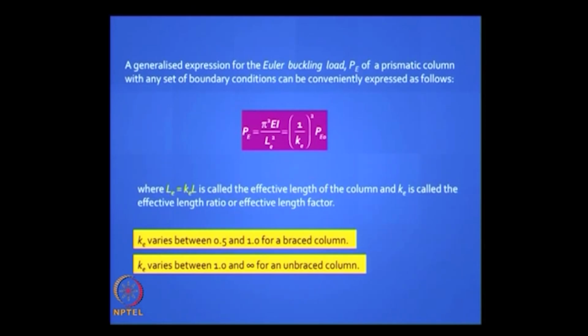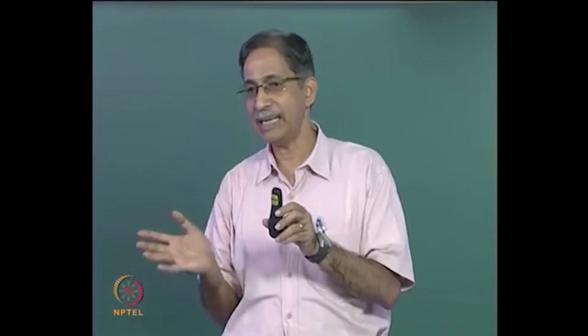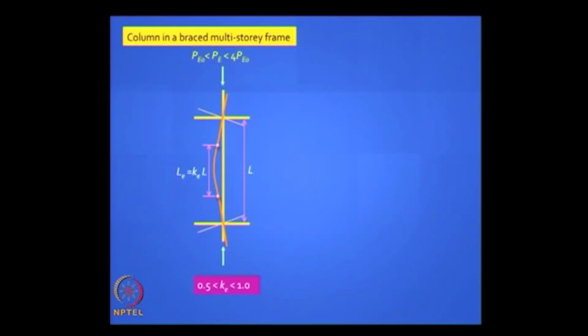You will have 1 when you have a guided fixed support at the top and fixed at the bottom. In a cantilever, it's going to be 2. And when do you get infinity? If both ends are pinned, it's unstable. Okay, so that's the other. Let's say you have a beam, you have a multi-storied building in a column, and the column has pinned ends. That means the beams have 0 stiffness. Then that's asking for trouble because it's going to sway like hell. It will be unstable.